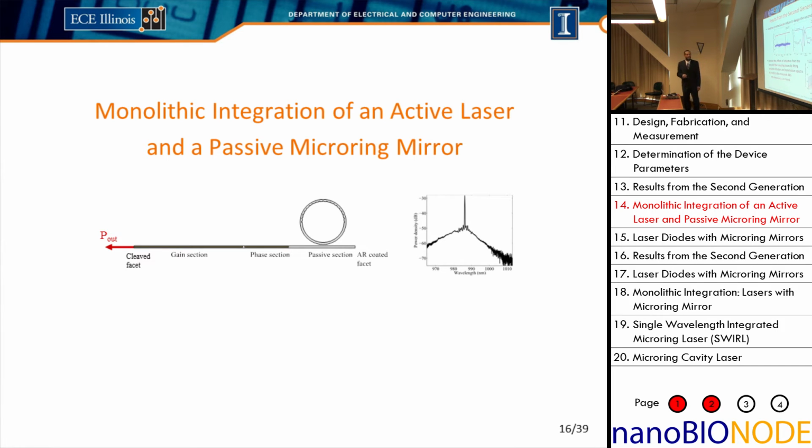So we achieved 93% reflection, 0.4 nanometer full width half max, and the overall structure is 70 times smaller than the conventional DBR structures that you'd find in a semiconductor laser. We got rid of the side lobes, and we also have a faster roll-off.